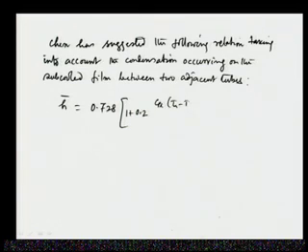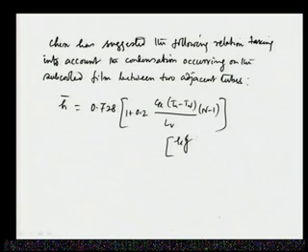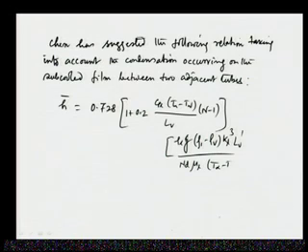And then there is a correction term like 1 plus 0.2 into C_PL, the specific heat of the liquid, into (T infinity minus T_W), divided by the latent heat of evaporation, into (n minus 1), where n minus 1 is the number of tubes minus 1 and n is the total number of tubes. So, this many spaces are there, and we have multiplied by the other things: rho L is more or less the same, g into (rho L minus rho V) into k_L cubed into L_V dashed, as proposed by Rohsenow, divided by n into d and mu L into (T infinity minus T_W), and then the whole to the power 1 by 4.